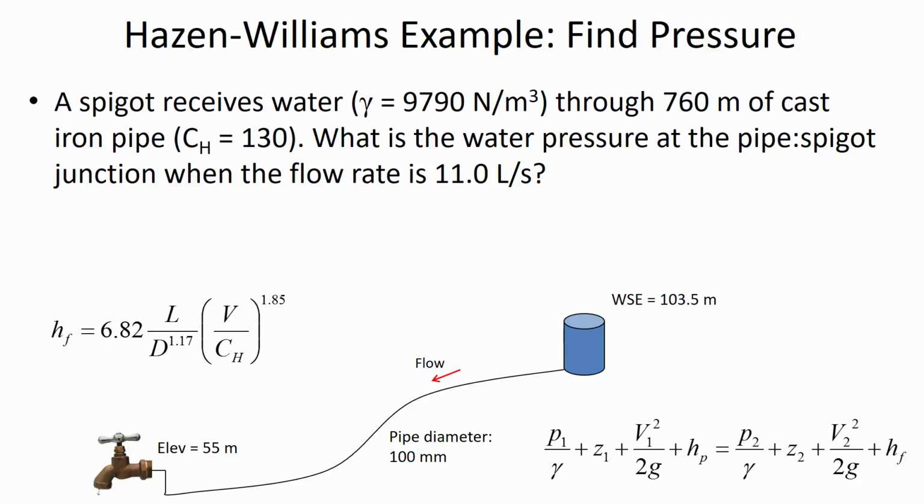This sudden drop is the energy that's lost as the water flows through the valve. And so that explains why when we were doing the first problem, we calculated there was 303 kilopascals of pressure available. Like if you connected a hose to the threads on that valve, and you opened it up and measured the pressure that's available as the water is flowing, it is the 303 kilopascals.